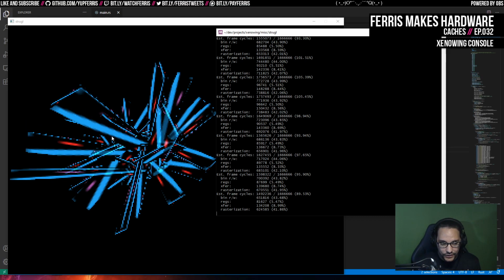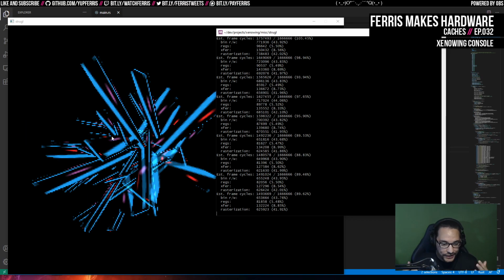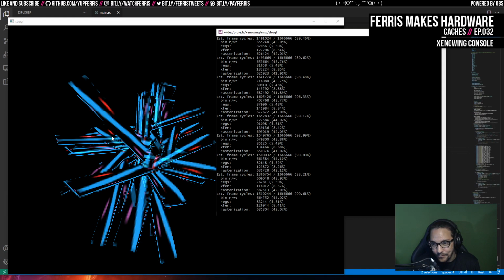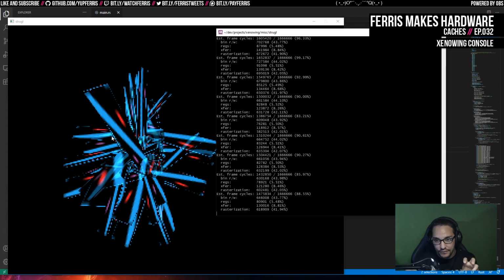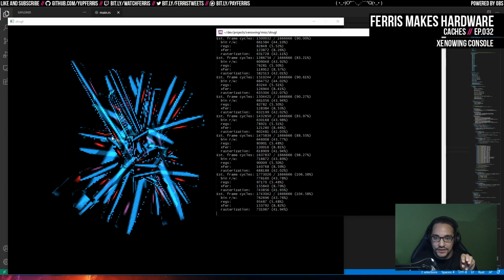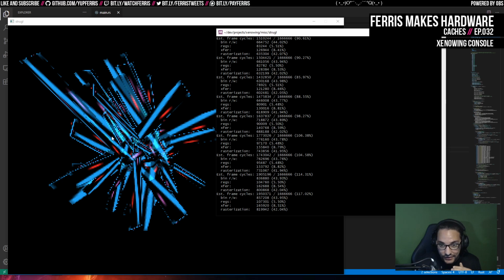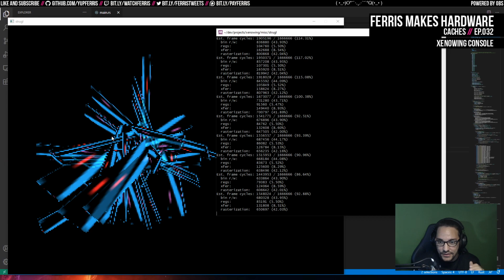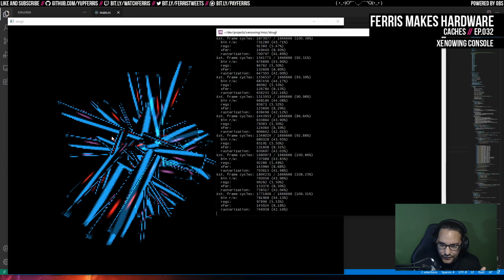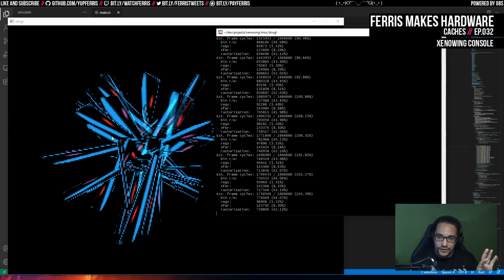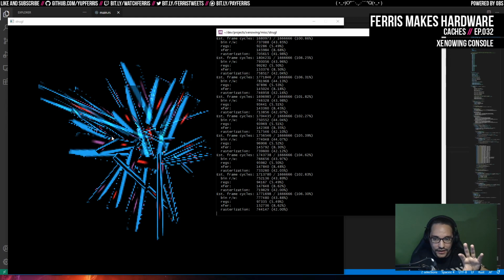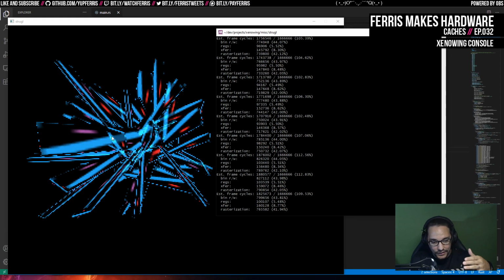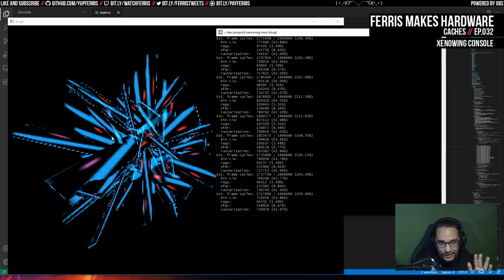So a better approach, with or without this tiled renderer, is to have a texture cache that acts more like a normal CPU cache. And this is what modern GPUs do as well, where you do mip mapping first of all, because then you can determine which levels of textures you might actually read. And it turns out you can probably save a lot of bandwidth just by not reading that much texture data in the first place. So that's going to be helpful. And second of all, the tiler will pull all the color and depth memory into the tile, and then as it's rasterizing, it will determine the texels that are actually needed and fetch those from main memory as it's rasterizing.